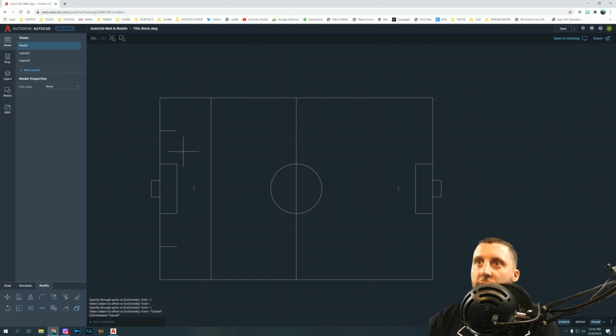Now you got a couple options here. You can use the extend tool to extend this. You can use fillet radius 0 and click from here to here, or you can even just grab these blue marks and drag that until it snaps for both. So that's probably the longest way, but you can do it any way you like.